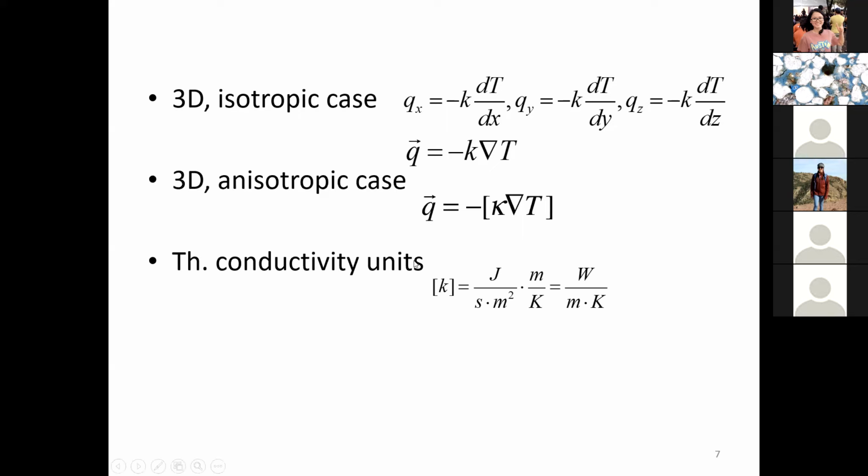Now, thermal conductivity units, we actually just had them mentioned in that exam, but they were given, are basically energy per time per area, times length per temperature. And you can actually figure that out from here, right? So this is temperature per length. When I put that on the other side, I get this term. So this is power, joule over second is watt. So this is power unit per length per temperature, okay?